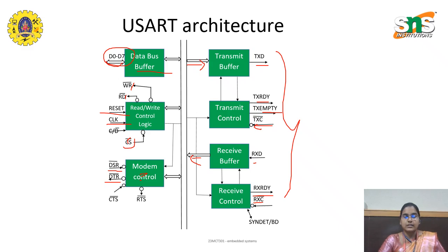In full duplex, a device can act as both transmitter and receiver at the same time. Compared to other architectures, UART and USART are very simple, and they can be configured with the key considerations of baud rate calculation and setting the data or frame format, and we connect them with the proper input-output ports.